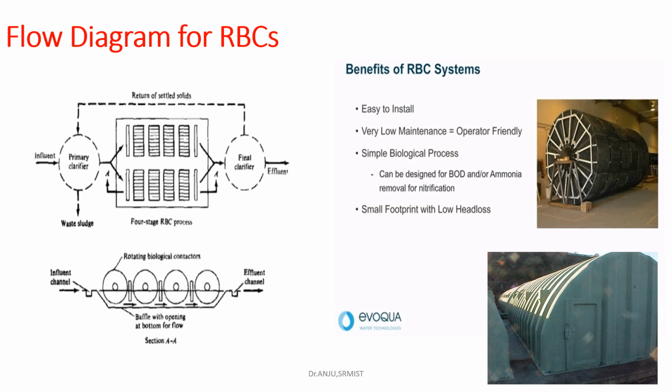The benefits of the RBC systems: it is easy to install, very low maintenance, and it is operator friendly. This is a simple biological process, can be designed for BOD and ammonia removal, and nitrification is done. So both BOD reduction and nitrogen reduction are also done with RBC systems.